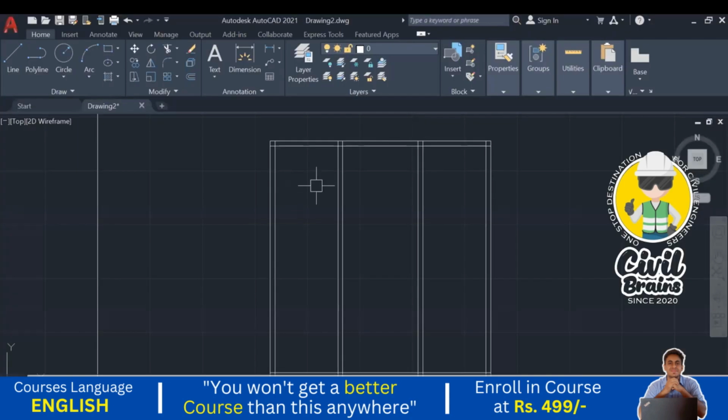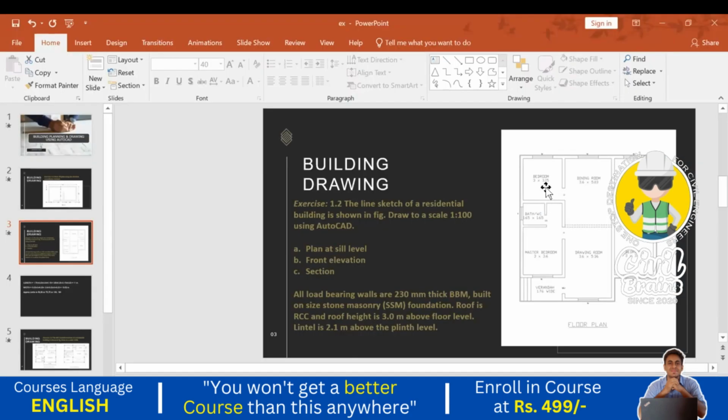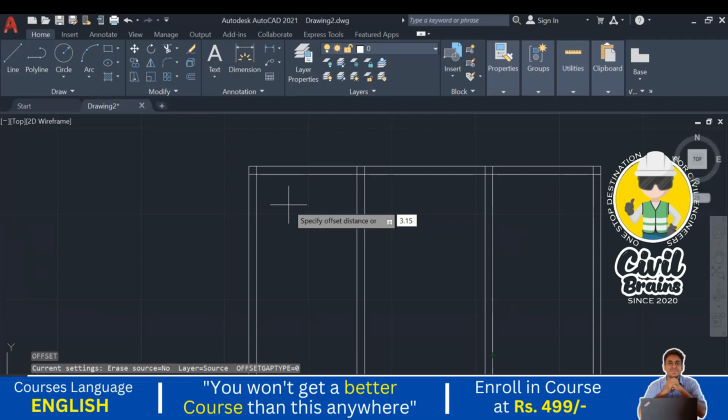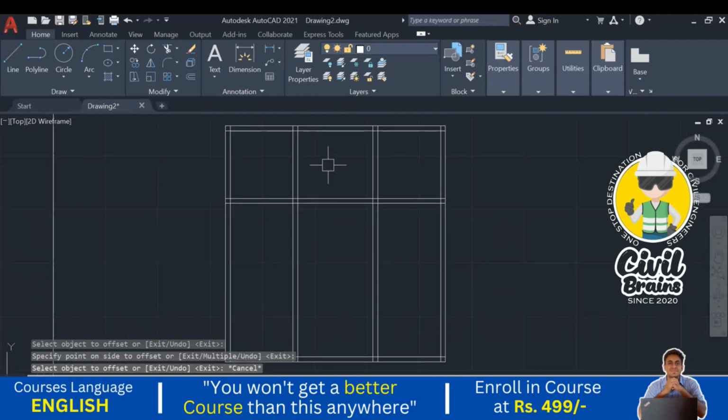Okay, so while drawing that one, I just go here first. Here I just go to the offset, press enter. What is the dimensions? 3.15 vertical dimensions, 3.15. Press enter. And what is the wall thickness here? Offset, enter. 0.23 is the wall thickness. Just enter. Okay, so now don't get confused.